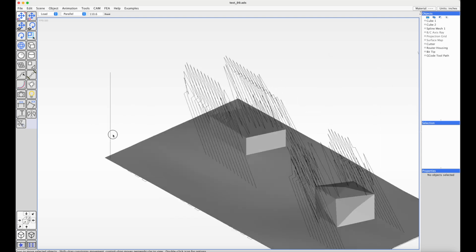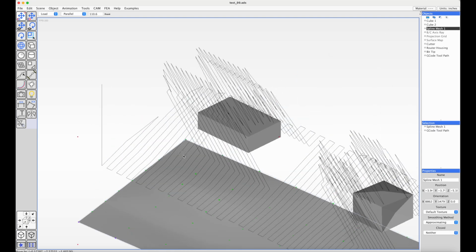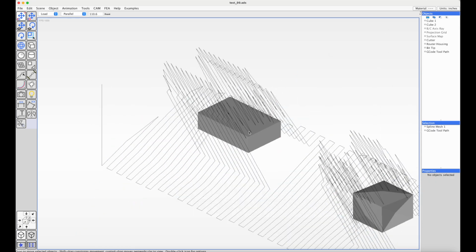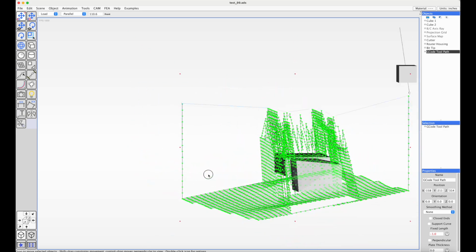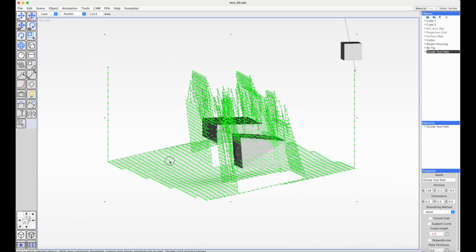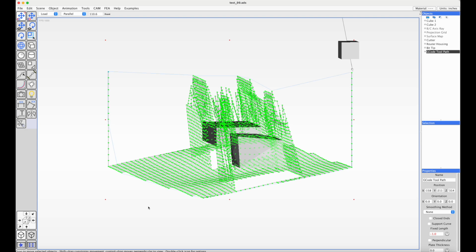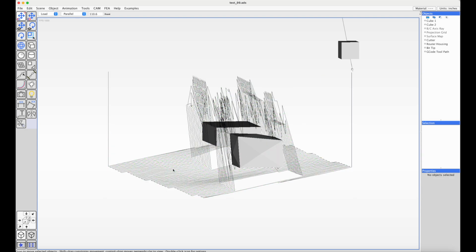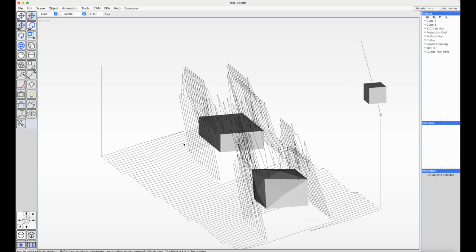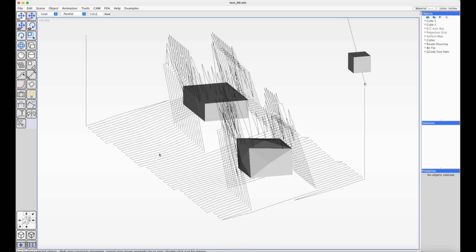So the one thing that this example doesn't do is it doesn't take into account the geometry of the milling bit or the drill bit. So the roughing bits are flat and some of the finishing bits are ball nose or round. Some of them could be different geometry.